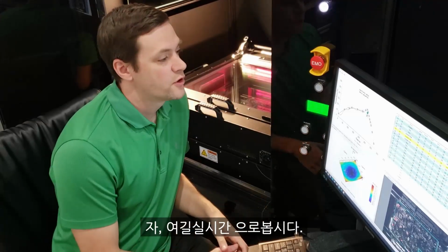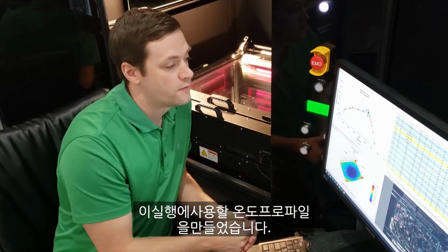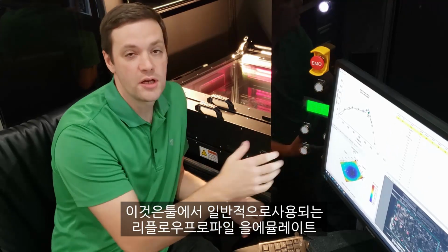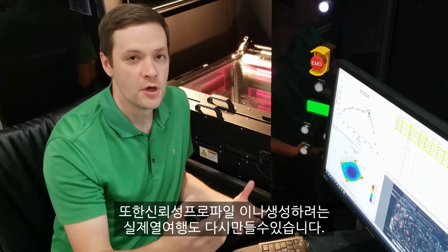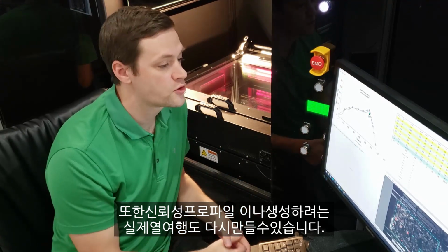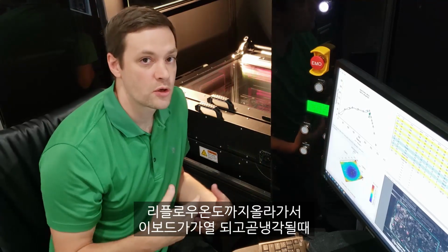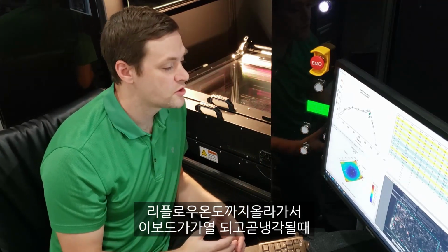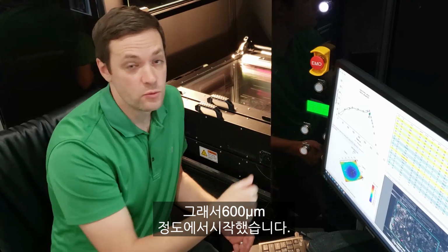All right, let's take a live look in here. I've made a temperature profile to use for this run. This is emulating a reflow profile, which is a common use of our tool. We also will recreate reliability profiles or really any thermal excursion that you want to create. But the system just took an image. We're going up to reflow temperatures and capturing the shape of this board as it heats and will soon cool.